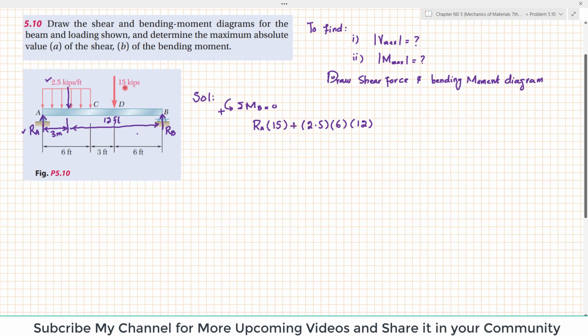The third force producing moment about point B is 15 kips. So 15 times the perpendicular distance, which you can see is 6 feet, so 6, and this is producing counterclockwise moment, so it will also be positive. Their sum must be equal to 0. When you calculate it, you will get RA equal to 18 kips. Kips means kilopound. Now we have the reaction force at point A.